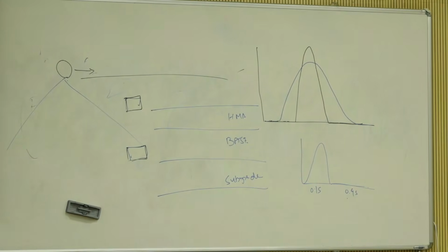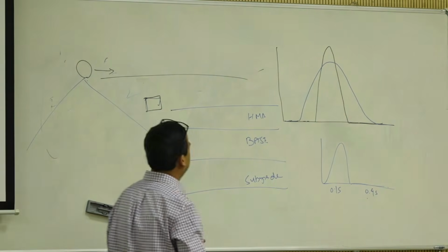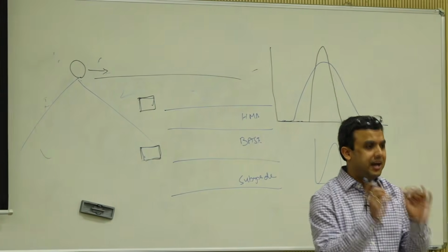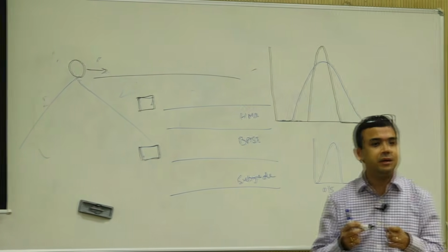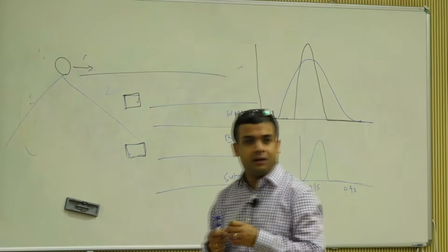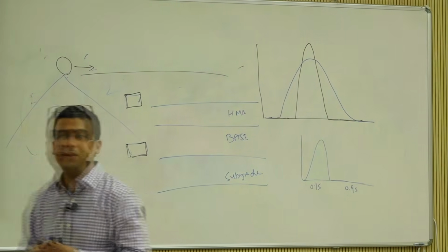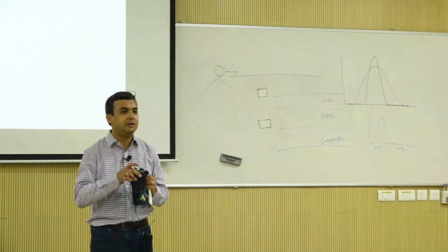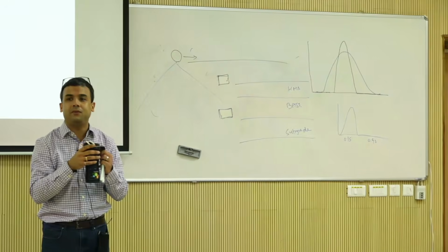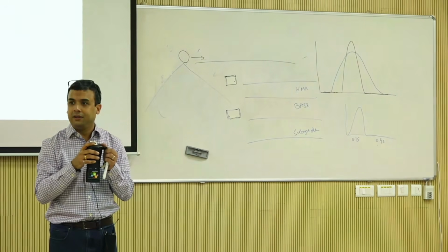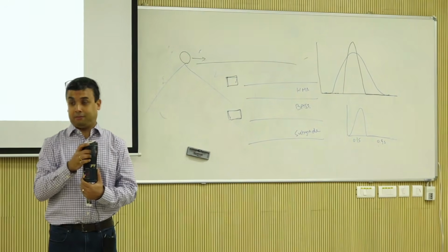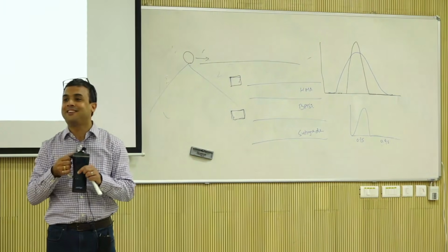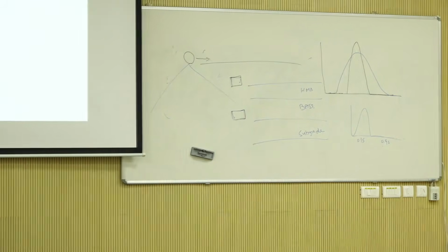Asphalt layer? No, you don't run resilient modulus test on asphalt. I'm talking about AASHTO T307, which is the actual testing that we did in the lab. For granular, have you done subgrade testing? How many of you have done aggregate versus subgrade? You have done aggregate, I know that. How many of you have done subgrade soils? What do you do? So one of you is wrong, right? The code says the same, so that's our excuse, isn't it?